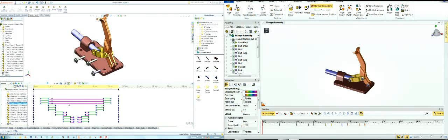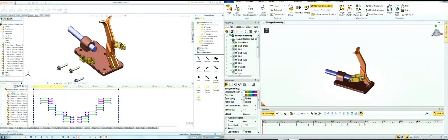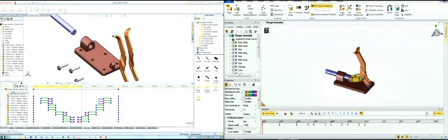So why do I have all this mess in the middle here? Well, because this says show, this says hide, the keys over here say show. So all I need to do is take these keys, and I can just copy these down to here someplace. Notice there's no change bar between them because nothing's changing. It says show, hide, hide again, so nothing changes, and then show. And now when I recalculate this, when the nuts go out, they'll fade out. I can do the same for all the other components, and most of them are already done.